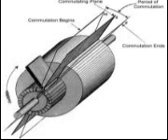Figure 9-12 shows a ring-type armature made up of an iron core, an eight-section winding, and an 8-segment commutator. This kind of armature is rarely used. Most generators use the drum-type armature. The drum-type armature, Figure 9-13, has coils placed in slots in the core, but there is no electrical connection between the coils and core.